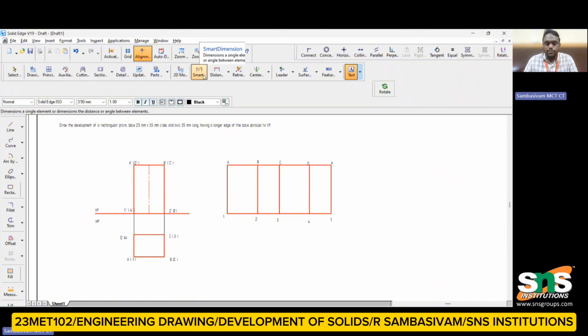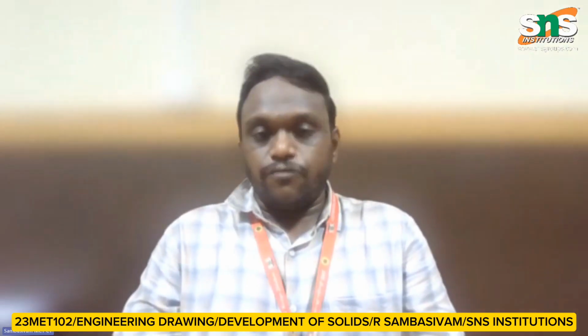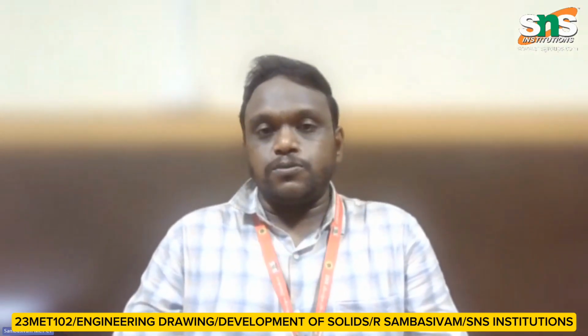For clear understanding of the dimensions, you can use the smart dimension option. When you click that, it shows the exact distance. The height will be shown like this, and the side will be shown like this. Similarly, the total length of this line, we can say, is 120, and this is 55. This is how the simple projection of a rectangular prism has to be drawn.